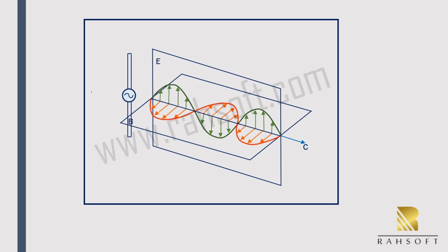Instead of the AC generator, the antenna can also be driven by an AC circuit, and charges radiate whenever they are accelerated. But while a current in a circuit needs a complete path, an antenna has a varying charge distribution, forming standing waves driven by AC. The dimensions of the antenna are critical for determining the frequency of the radiated electromagnetic waves. This is a resonant phenomenon. When we tune radios or TVs, we vary electrical properties to achieve proper resonant conditions in the antenna.